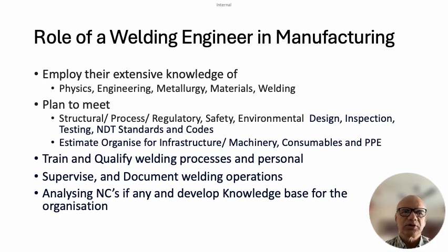The first step of execution is to train and qualify the welding process. Once you get the requirements as per the welding process and the standard which you are following, let's say we are following Section 9, then according to Section 9 we will be classifying the materials in different P numbers, consumables in different F numbers, and then we will be writing down what parameters we are going to use. If we are going to have an impact property, then the supplementary essential variables are also going to get listed,